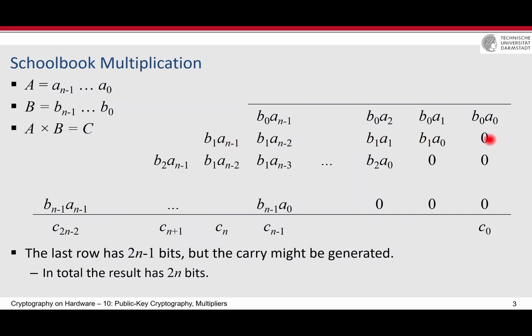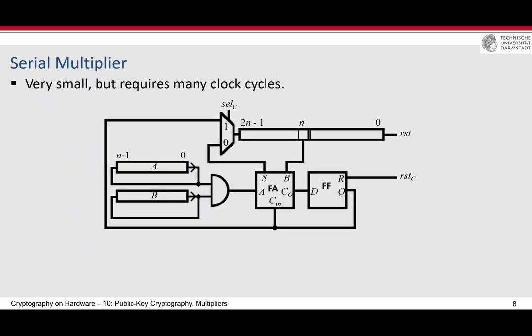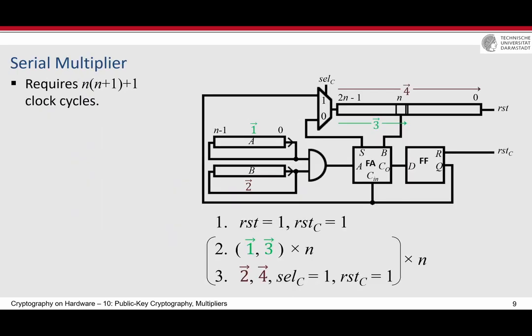then suppose that I already made this and I added everything. Then I have a vector of intermediate values up to this row, and then I take this and add it to all the values that I already stored, and then the carry of this goes to the next addition that I have in this column, and so on, but only with one full adder, and for that I need a register to store the carry. How this works, this is the procedure.